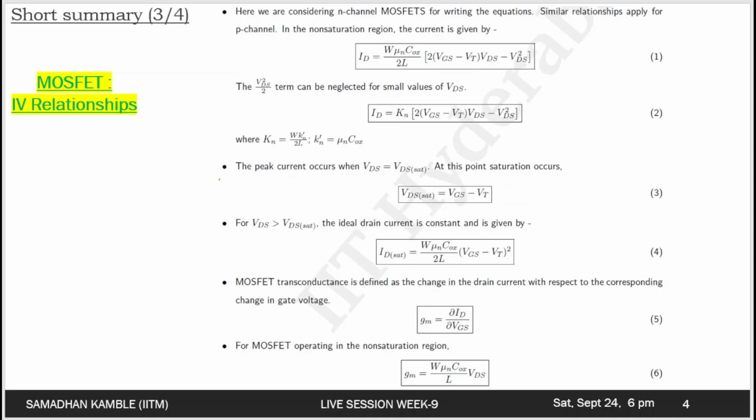The greater the applied gate voltage in excess of turn on, the larger the conductance of the internal channel at a given drain voltage, and a non-zero drain voltage in turn initiates the current flow between the source and drain. The current flow is proportional to VD at lower drain voltages, and it slopes over due to the narrowing of the channel as VD is increased, and eventually it saturates once the internal channel vanishes, or so-called pinches off, near the drain. So a summary of different formulae for all of this is given in this slide.